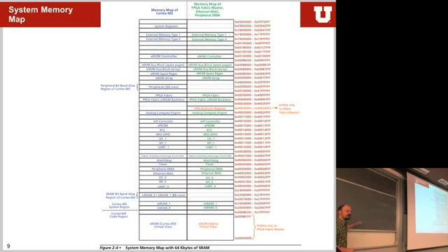If you write into it, you will change the status of that I/O line. Okay? So how do you make sure that you only change, for example, bit number 30 without having to go and change any of the other registers? You create a mask. You can create a mask, yes.